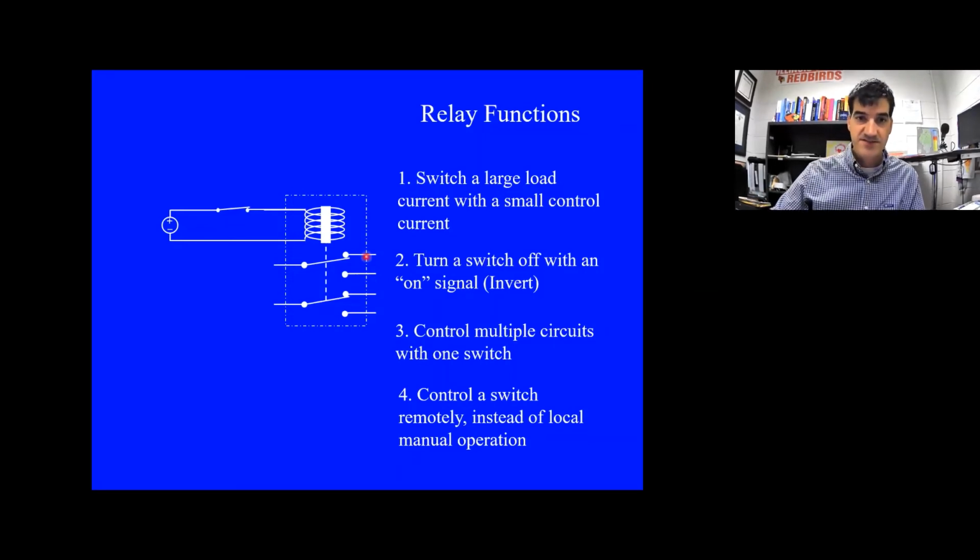So if you have this type of switch, double pull, double throw, you could control 2 circuits. You got 2 commons, so you can control 2 circuits, but you can get relays that are 3-pole or 4-pole or even more. They get a little more expensive, but you can control a lot of different circuits with ultimately just one switch. Just this one right here can control all of these circuits down here in the switch part of the relay.